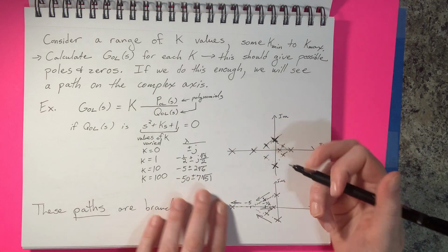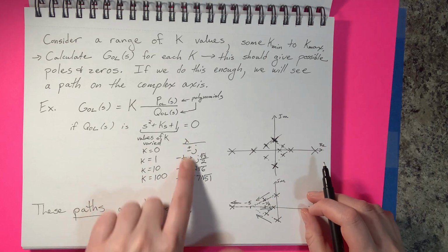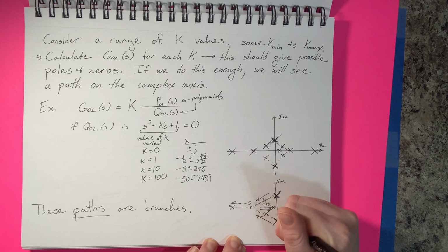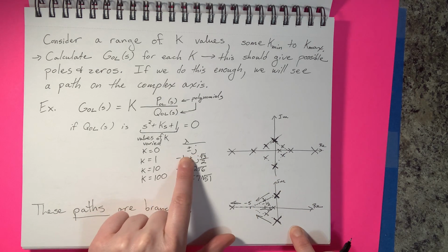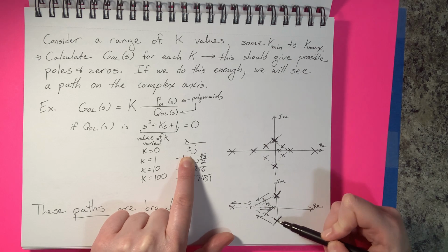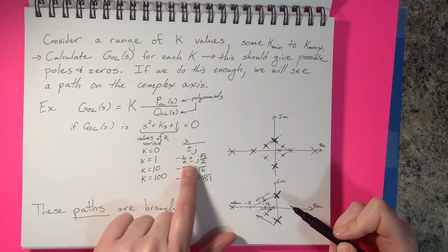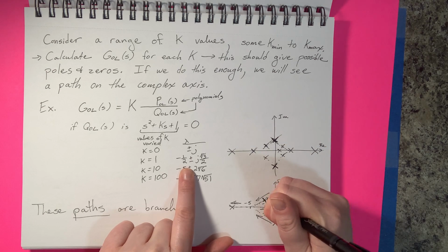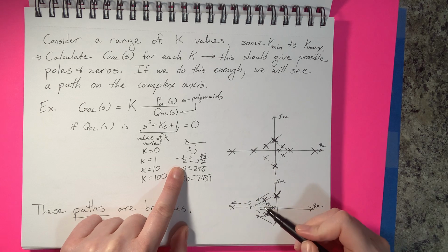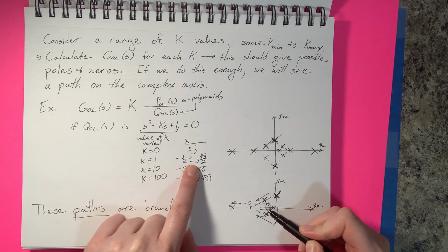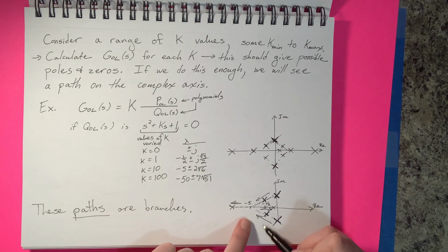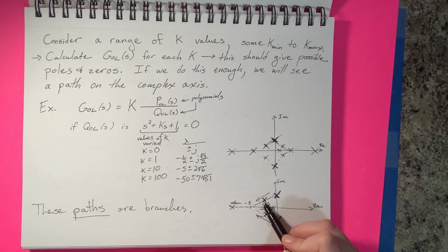So we start, and now this is the plot that corresponds to this trend. So we would plot first this pair of poles right here, and this is plus minus j, so it's on the imaginary axis right here, I mean. And then the second pair we would plot out here. So they have a negative real part, so negative 1/2 is this point right here. And then we have a plus minus j value, so they're still in the complex plane. They have a non-zero imaginary part.